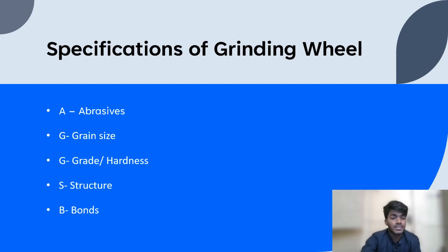The abrasive is the type of material used as abrasive grain, which depends on the hardness of the material that it grinds. Some examples of abrasives are aluminum oxide, silicon carbide, ceramic, diamond, boron nitride, etc. Grinding wheels prepared using diamond and cubic boron nitride are referred to as super abrasives. Those constructed with aluminum oxide, silicon carbide, ceramic are referred to as conventional abrasives.